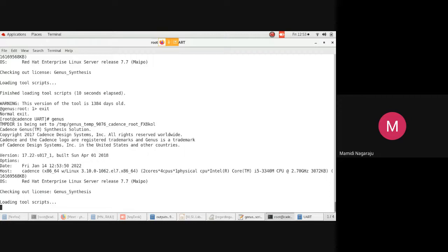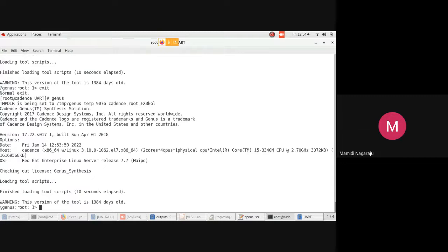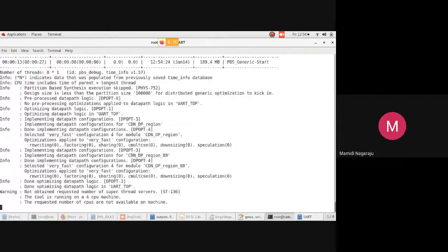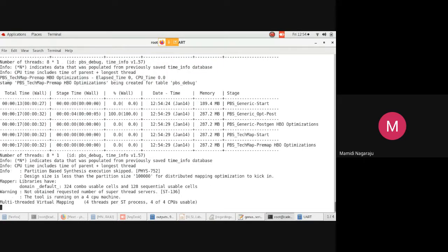Now I'm opening our constraint design. So there are three cases. First case 40 nanoseconds, second case is 10 nanoseconds, and another case is 0.2 nanoseconds. So three types of constraints. One is a reliable constraint, over constraints, under constraints. Okay. So I'm now applying the over constraint case. There you can find timing violations. So some worst negative slacks.